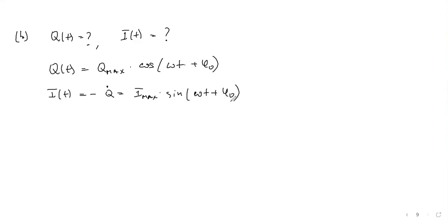So when I have initial time moment, when I just start motion, my current was 0. It tells me that the phase shift could be 0. And then my charge was maximum, and then it will start to discharge, it will start to decrease. So I'm kind of comfortable with phi naught equals 0. It will give me the right solution. And also Q max will be just my initial value, yeah? It will be just 10 microcoulomb. So I'm gonna try to satisfy what we call initial conditions.